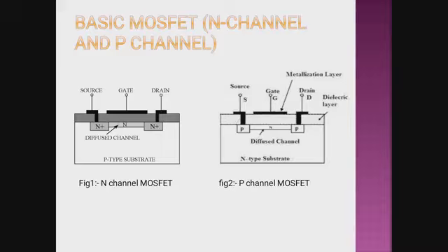This is the sandwiching length which has been created in between source and drain. That is why it is called the channel diffusion. And the current is entering through the source terminal, as I told in the previous slide, because source terminal means the terminal through which majority carriers are entering. So current will flow from source to drain through this channel, through this diffused channel.